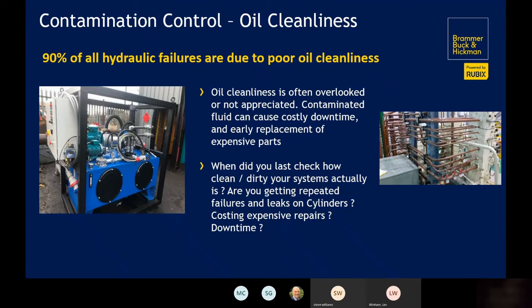On to oil hydraulic cleanliness. With our new hydraulic centres, we are now able to offer you contamination control on your hydraulic systems. The concept of this works similar to the other CBM technologies. We install a particle counter onto your running power pack, which checks constantly over 10 to 15 minutes the status of your oil, logging particle counts and other information.